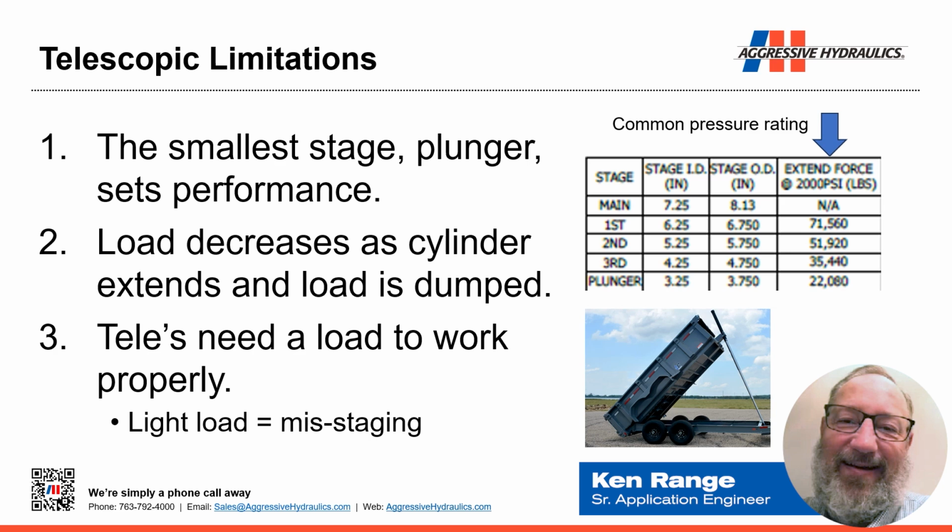In actuality, the weight that a telescopic cylinder is trying to move has to be within the capability of the plunger stage, period. Even if the previous stages are more powerful, I'm afraid it's just a fact of the way a telly works. If the plunger stage can't move the load that you're trying to move, it doesn't really matter.